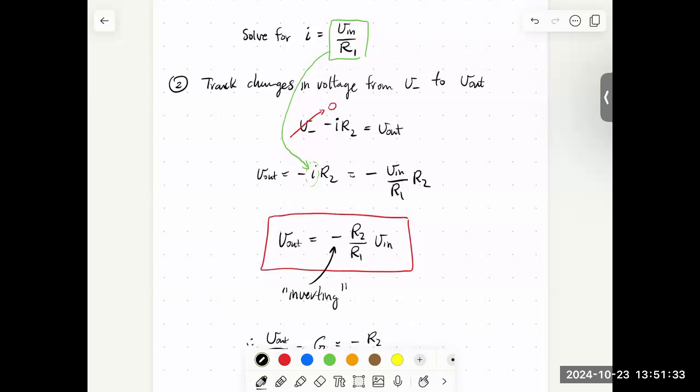What if I took 2 inverting amplifiers, one after the other? I make one with a gain of -10, and I make the next one with a gain of -10. And so there I would have a gain of +100. What if I wanted to do a gain of +1/100? I would make a gain of -1/10, and then follow it with another amplifier of a gain of -1/10, and I would get a total gain of +1/100. So that's possible by cascading a pair of inverting amplifiers.